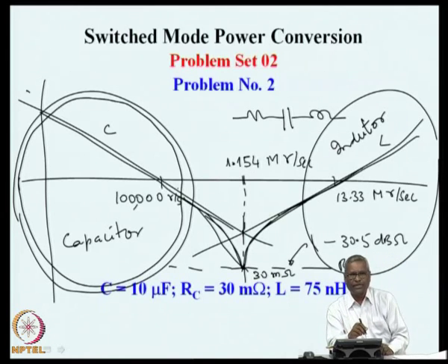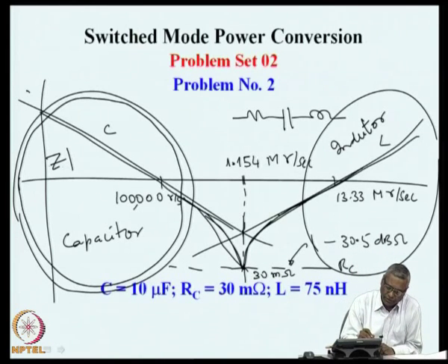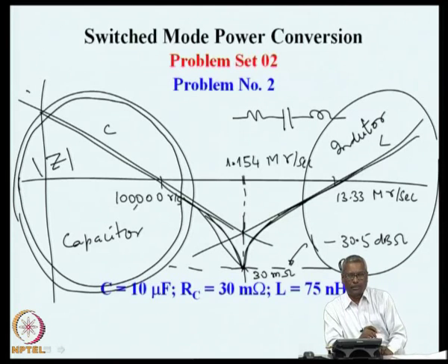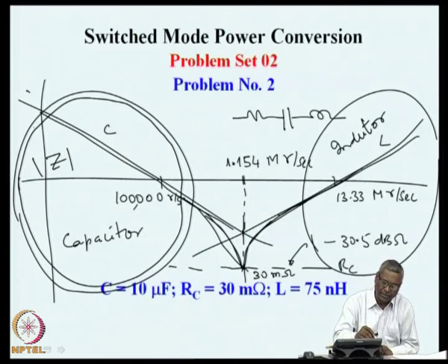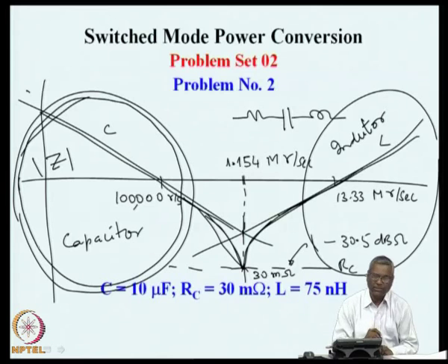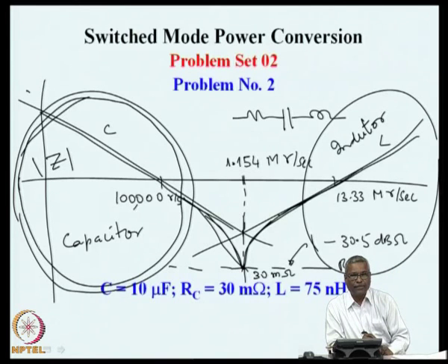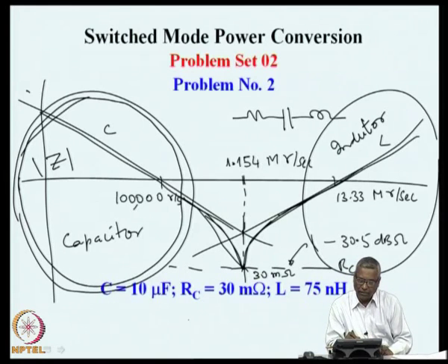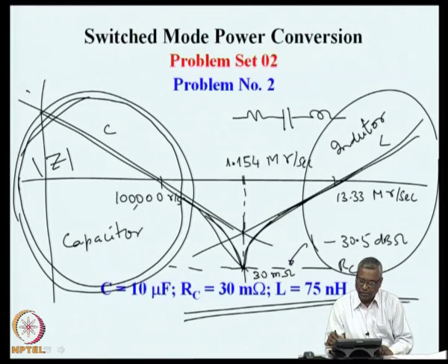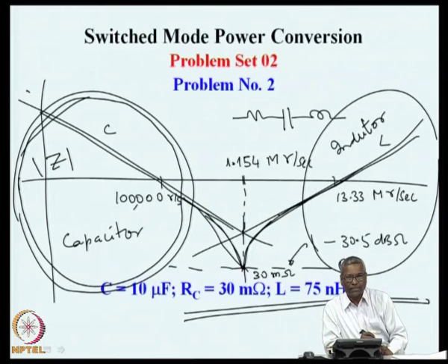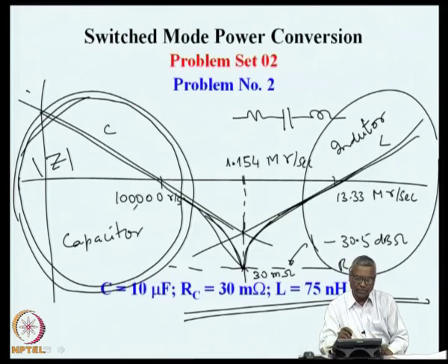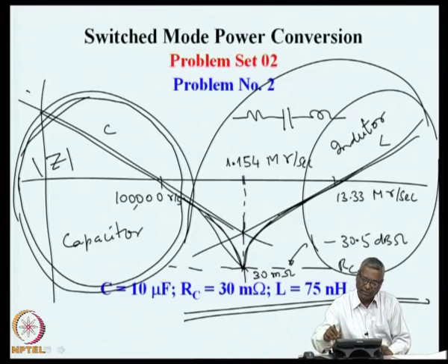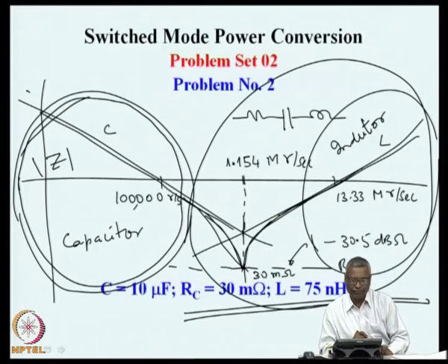So, this type of impedance diagram is very useful in evaluating circuit elements along with all their parasitic quantities. From this it is possible to identify the frequency range in which this circuit element behaves close to the ideal, and the frequency regions where it is dominated by the parasitics, and it is better to avoid those areas where the parasitics dominate the overall performance. Okay.